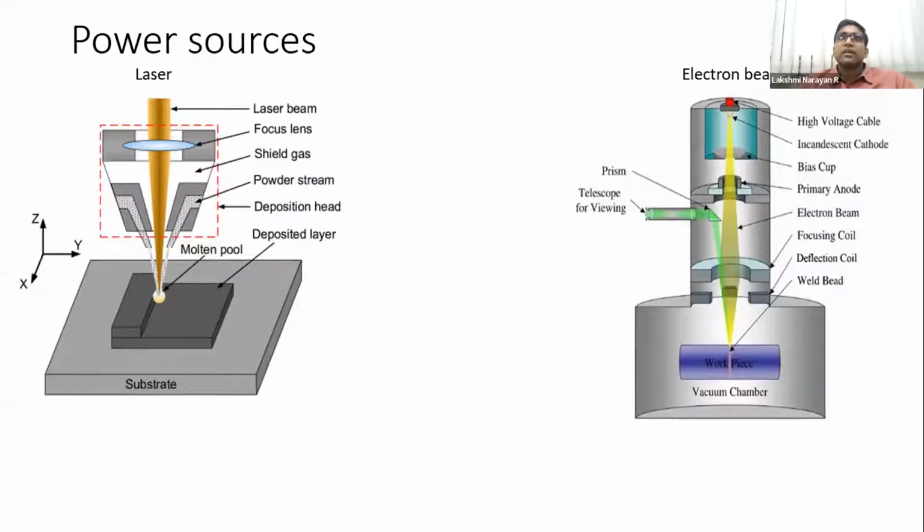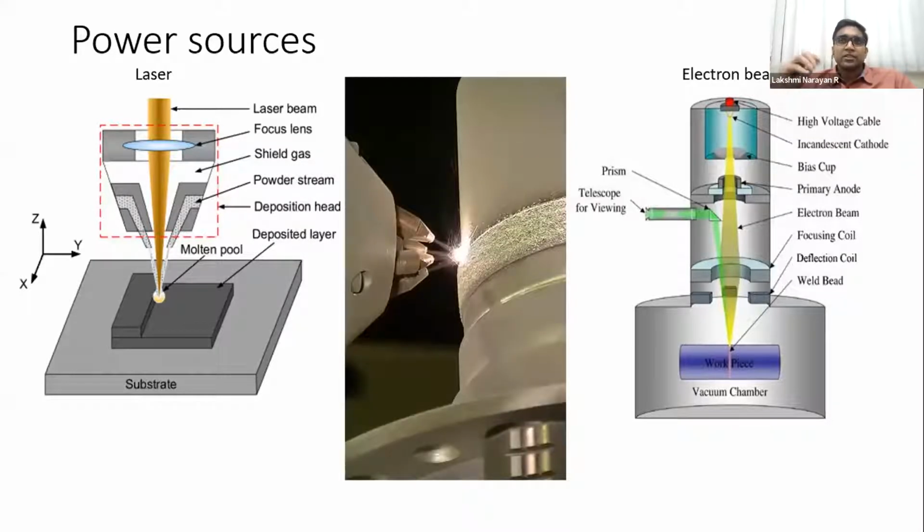Of course, with electron beam melting, it is generally heard that the dimensional accuracy can be greater. And it is also used for, let us say, printing these superalloys more often, of course, for aerospace application. But having an electron gun itself is a costly problem. Instead, a laser bed is relatively cheaper. Of course, there are some issues if you go for very high power lasers as well. But generally, you can do some kind of printing in situ in some cases.